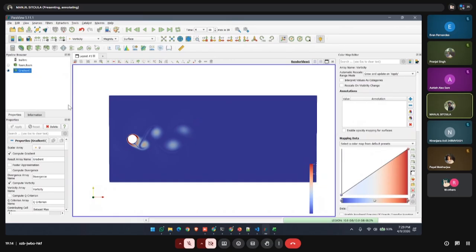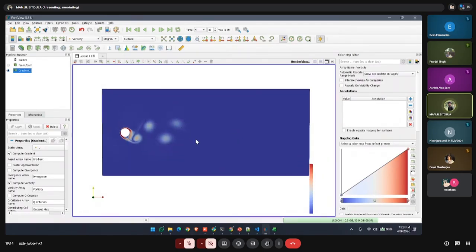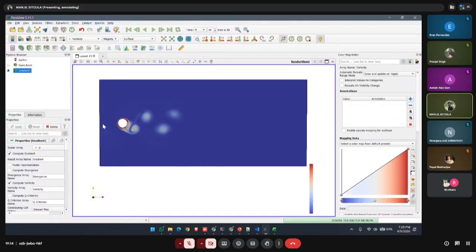So these are the small required things that you need to set up a dynamic mesh case. Now, for accuracy, you need to properly validate and change different solver settings, and you need to change the motion diffusivity and all those things. But this is to briefly show how we can set up a case from scratch and then start building up to an oscillating cylinder case, an oscillating airfoil case, a combustion or a piston simulation case, and all those complicated cases.